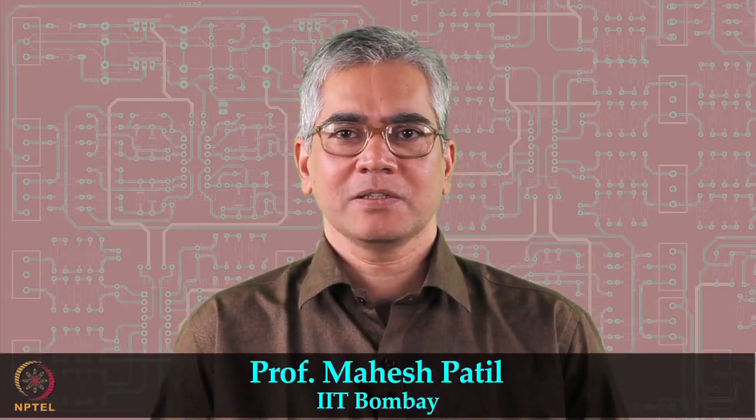To summarize, we have looked at the super diode, a combination of a diode and an op amp, which behaves like an ideal diode with turn on voltage equal to 0. We then looked at an interesting application of the super diode, namely AM demodulation. After that, we have started looking at precision clipping and clamping circuits. We will continue with this discussion in the next class.